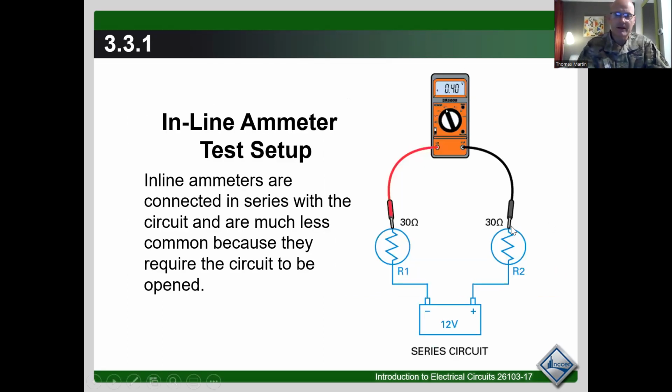This shows how to use an ammeter in line. Now, this is DC. I can't tell you how many times I hand out these meters to young men and women, and next thing you know, they blow the little fuse inside because the first thing they did was go to their outlet and test it. Our outlets are on alternating current.